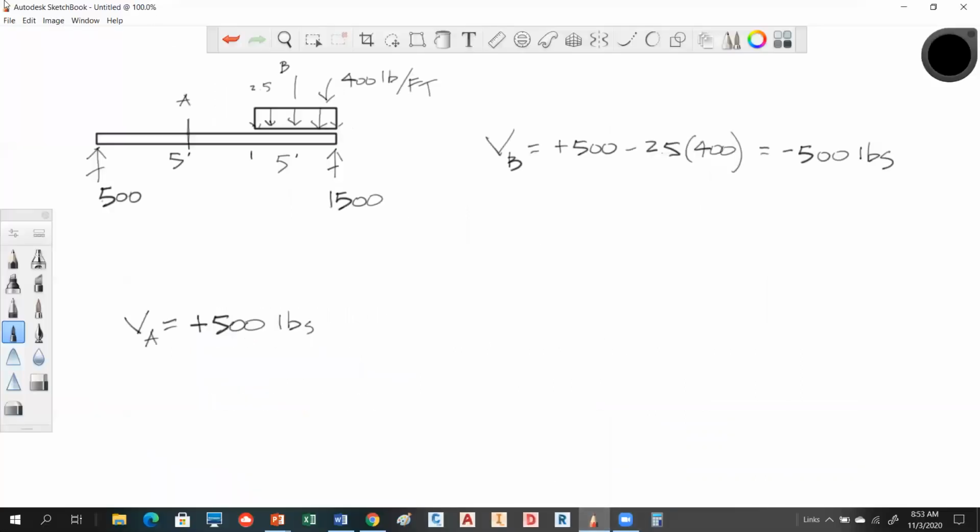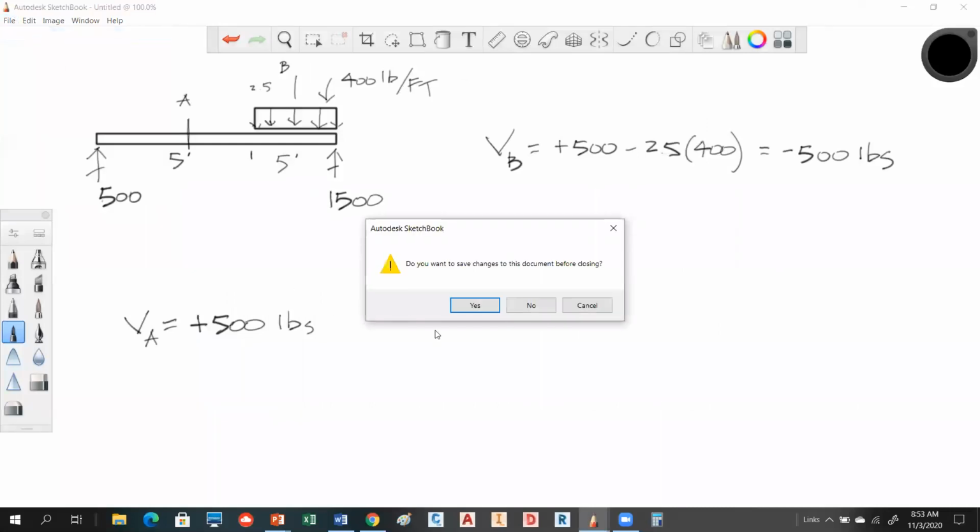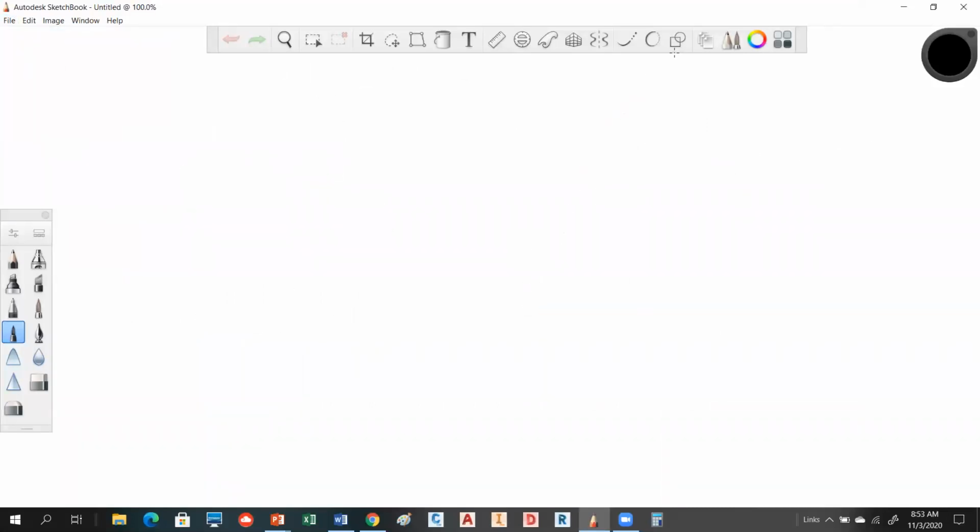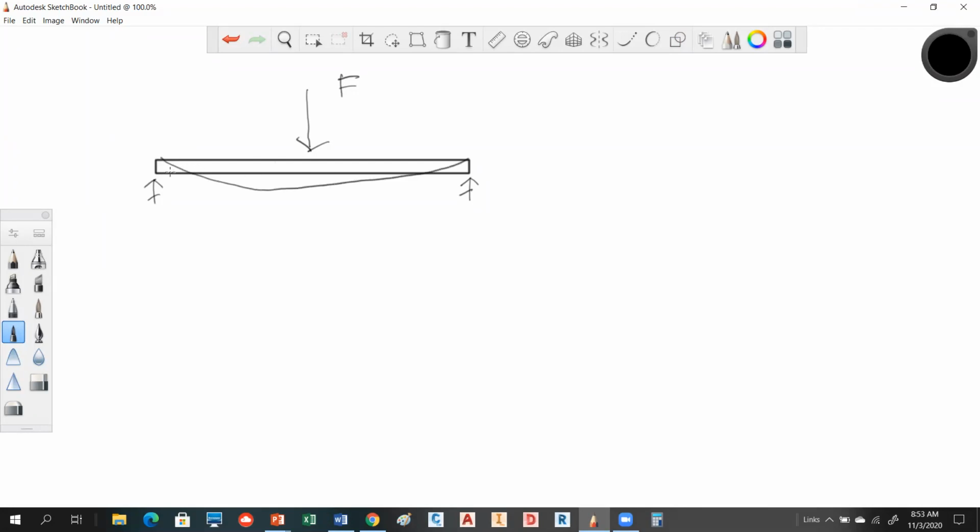let's go back to this. If we look at this, I'll try to do this the best I can. It's a little hard to draw with this, but if we have a normally supported beam like this, and you've got this thing supported simply by, you've got a reaction here and a reaction here, and let's just say we've got some concentrated load of force here. What moment's going to try to do to this thing is bend it like this, right? And this amount here is referred to as deflection. And if that deflection gets too severe, it could fail your beam.